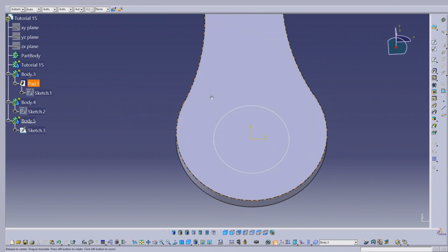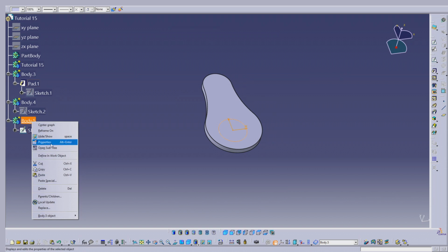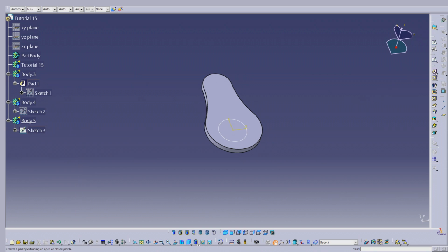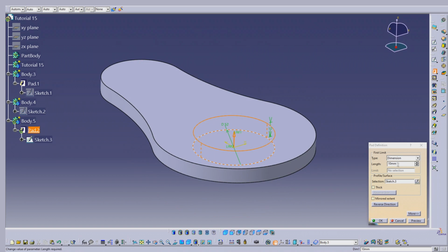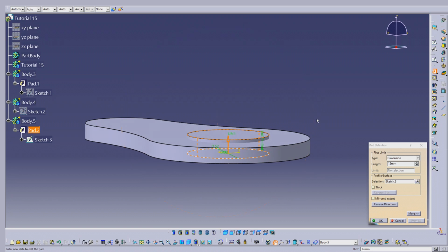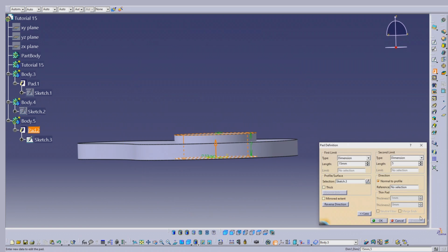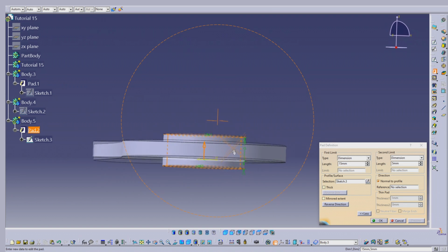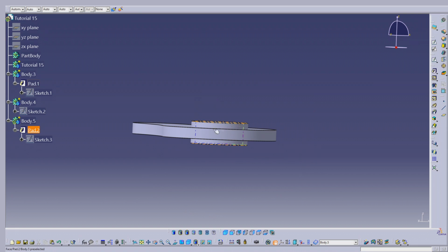Now we're gonna exit, and now we need to construct the 3D for this one. So the define should be on the body where we work. We're gonna select this body, select this sketcher, and put it 12 millimeters in this direction, because we need 10 millimeters plus 2 millimeters the thickness, or let's try 15 to be much better visually. Now we're gonna select more, and this distance from here we're gonna put 5 also. We're gonna select OK, because we're gonna have it in 2 directions.